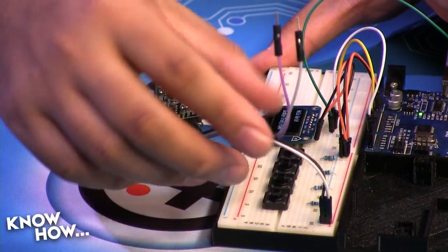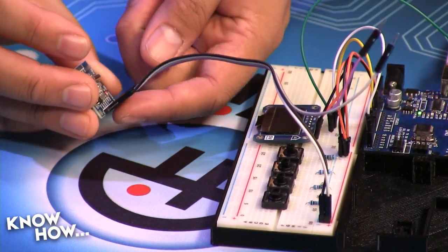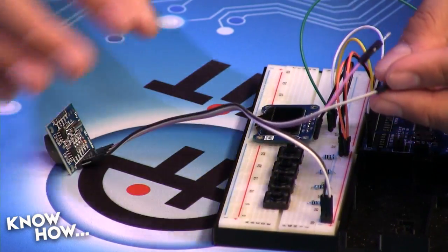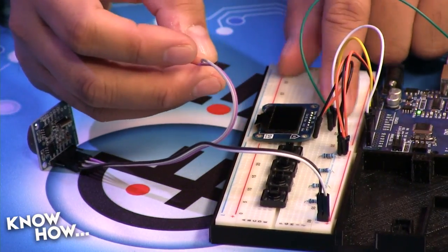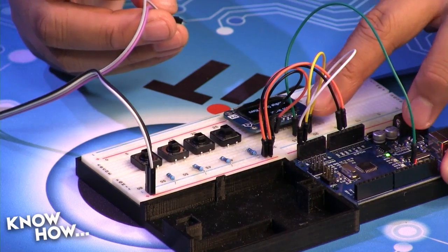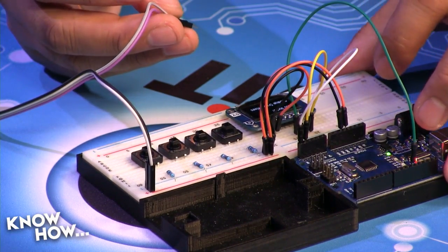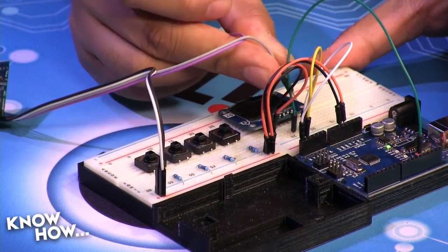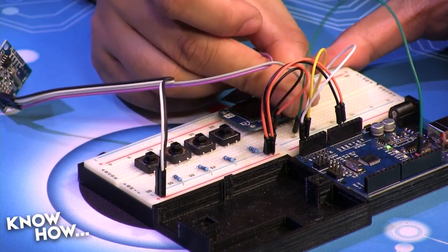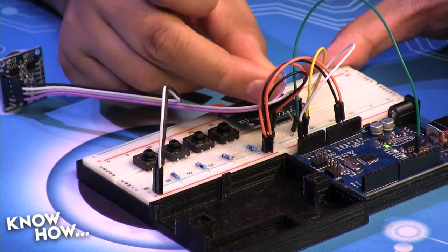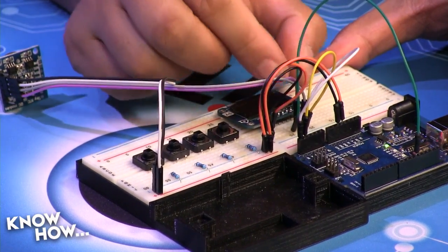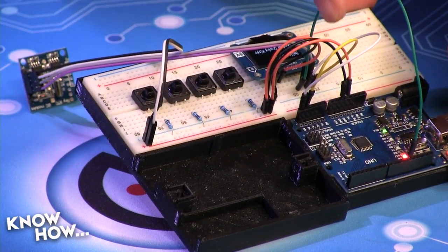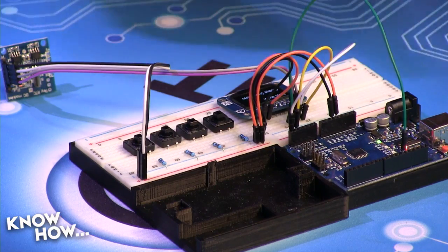So now I've got power to my device. And on this, my SDA is gray and my clock is purple. Remember, yellow here was my data and white is my clock. So I should be able to do this. Same lines, right? Just plug it straight in and straight in. So these two devices are literally connected, because anything that's vertical like that is the same line. They are connected to the same wire.